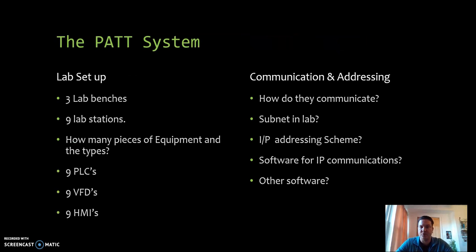So the PATT system, we should be familiar with the lab setup as well as the communication and addressing. So we got 3 lab benches total, 9 lab stations, how many pieces of equipment, and the types. So we have 9 PLCs total, 9 VFDs total, and 9 HMI screens total. As far as the software used for that, we should be familiar that it's RSLinx Classic. So RSLinx Classic is our Ethernet communication software.